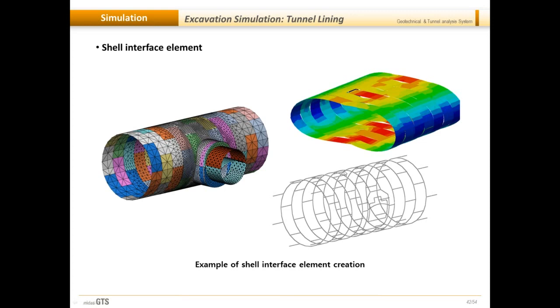And then you can see the results and the behavior. So you can see how these tunnel lining members are actually interacting with the adjacent members. And you can see if the maximum of the tunnel lining member occurs at one location in one lining, it may not be exactly the same for the adjacent lining. So depending upon the interface, the force transfers vary. And here we have simulated the rolled condition, so therefore the forces and the stresses are varying as you go along the length of the lining, and this gives you much more confidence on the analysis that you have performed and on the results, and you can actually optimize your design results and save on your material cost.